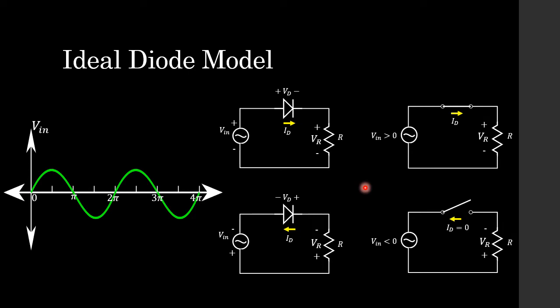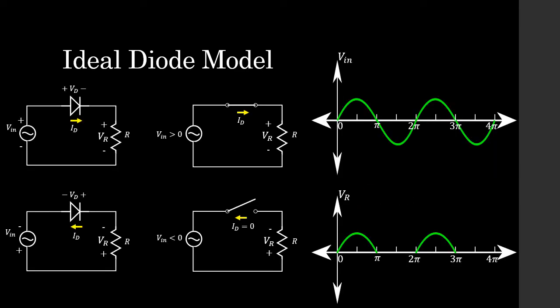And what does the output voltage, or the voltage across this resistor, look like when we take a measurement? Well, students, here we have it. If you were to go into the lab and take your multimeter and measure the voltage across this resistor, you would see an output voltage that looks like this, because our diode only conducts in the forward biasing condition, and in the reverse biasing condition, when our input voltage is less than 0, current is not allowed to flow, and therefore we have what is called a rectified output across our resistor.